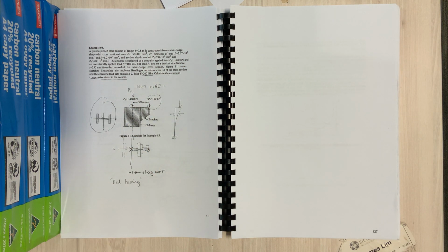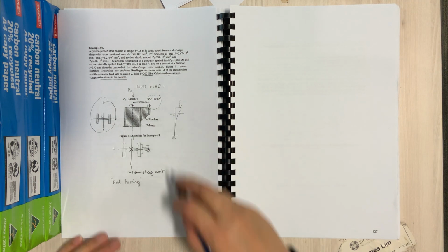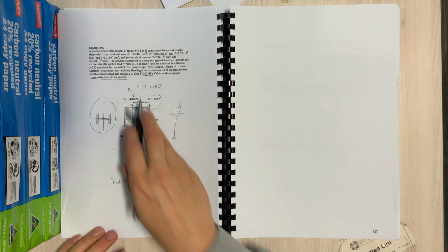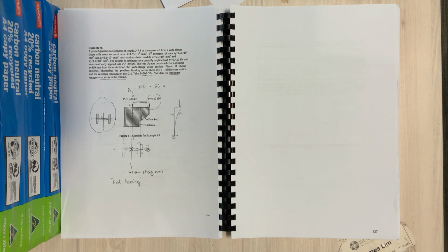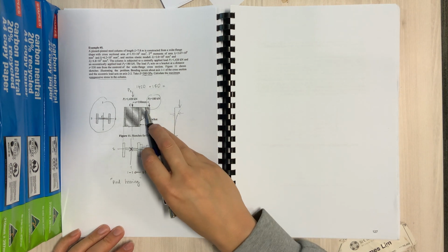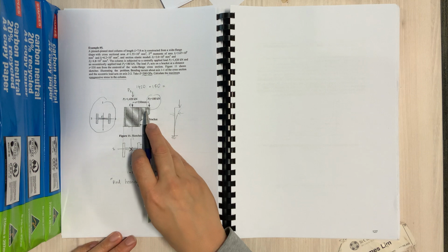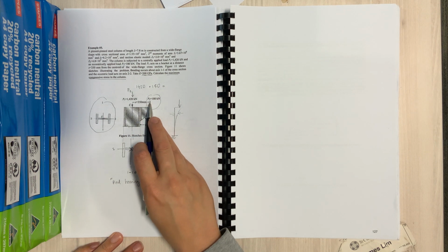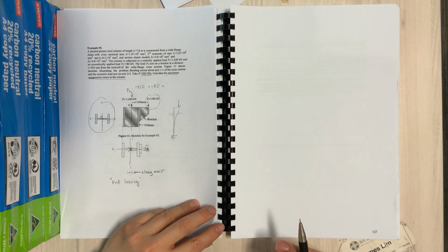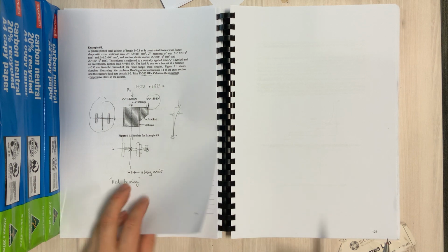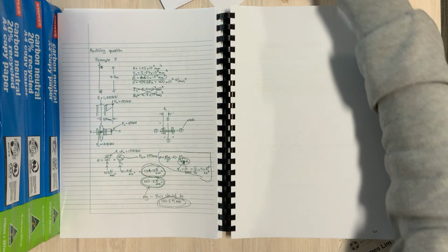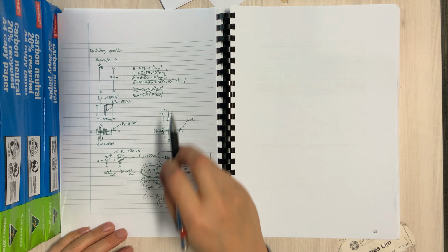So that would be the axial component of the stress, but that of course ignores this bending component of the stress, influenced of course by the fact that a column wishes to buckle, and also that there is an eccentric load being applied at the bracket. So this is what we have here.